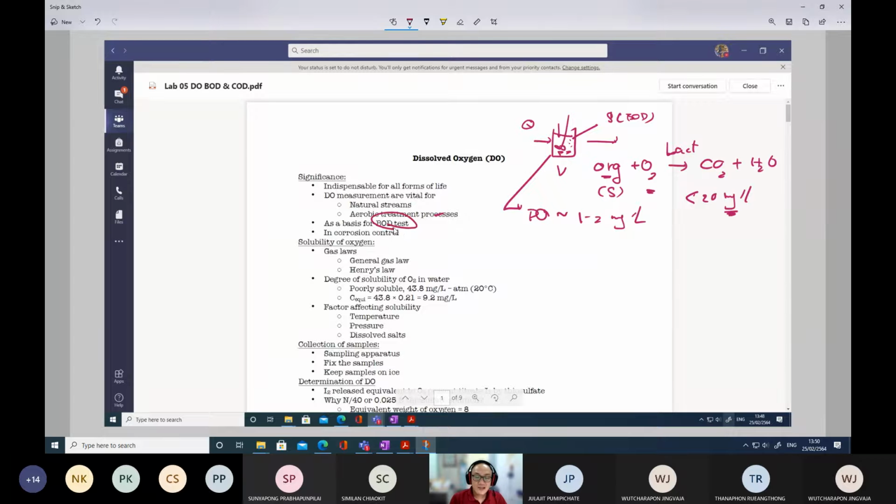And then for the BOD test, in the BOD analysis, we have to measure the dissolved oxygens on day zero and compare with the dissolved oxygens on day 5. On day zero, we measure the oxygens. The oxygen should be very high, for example, 6 milligrams per liter. Then we keep this bottle for 5 days, and then we measure the dissolved oxygens again. During these 5 days there is degradation, so a certain amount of oxygen is consumed by the microorganisms. After 5 days, depending on the amount of organic substance present, it may be 2 milligrams per liter. So 6 minus 2 is 4 milligrams per liter, and these 4 milligrams per liter can be considered as the amount of oxygen consumed.